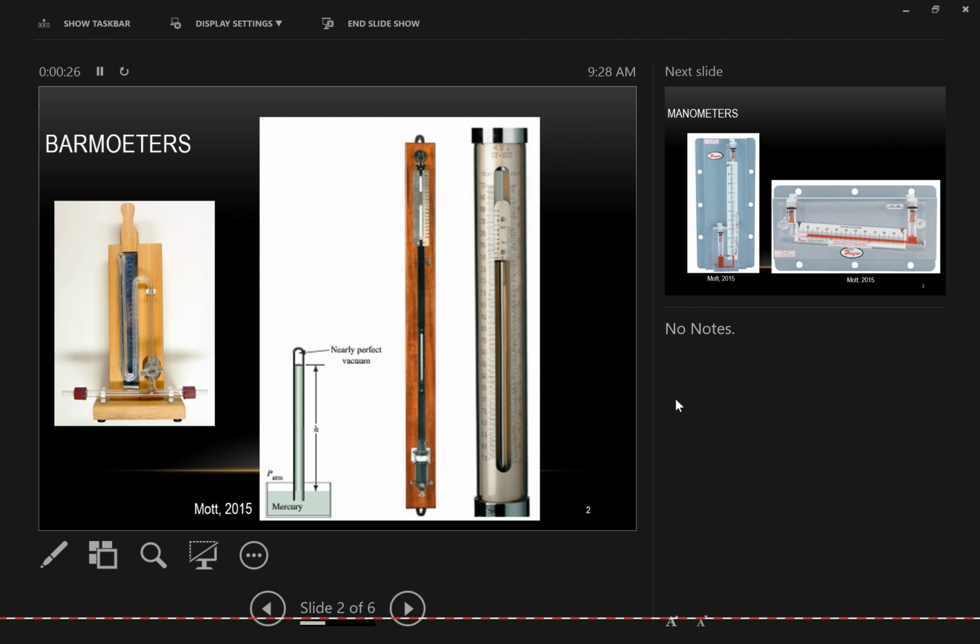Okay, so the first thing that measures atmospheric pressure only are called barometers. So basically, this is the fundamental concept of a barometer. In here, we can almost consider it a vacuum. The pressure is zero. And atmospheric pressure is right here, pushing down on the fluid here, which then can raise or lower this liquid depending on when the pressure changes. Okay? So, if this is mercury interface here with the air, what's the pressure right there?